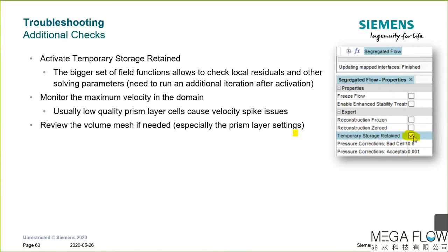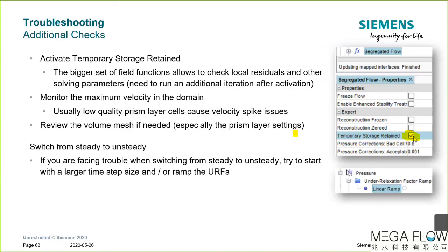And a final comment about switching from steady to unsteady here. It can be beneficial in some cases to start with a larger time step size or play around with the under-relaxation factors.